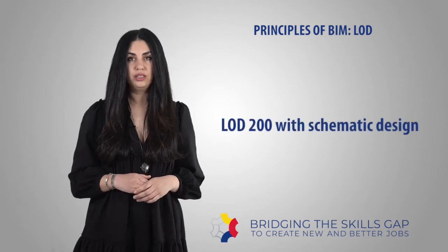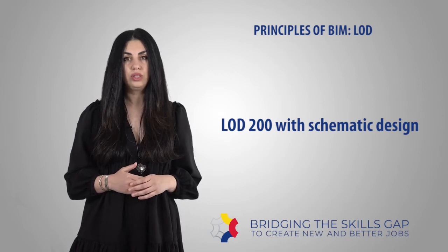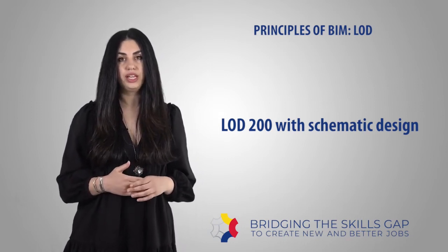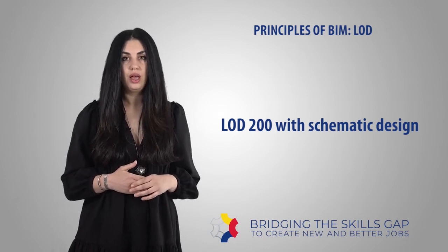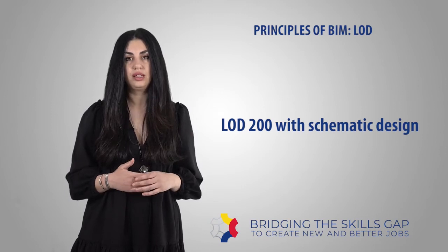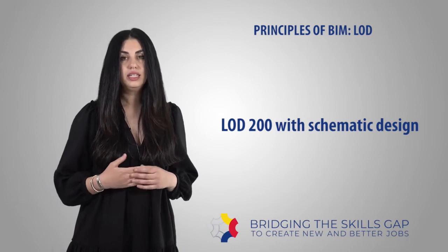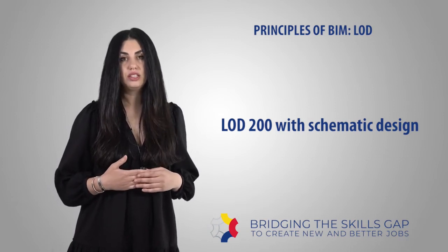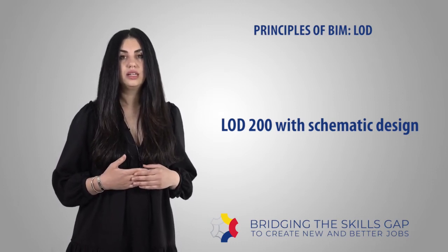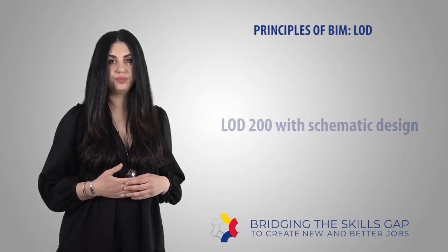LOD 200, schematic design, a general model where elements are modeled with approximate quantities: size, shape, location, and orientation. We can also attach non-geometric information to the model elements. With LOD 200, as you can see, this column starts to take the shape of a steel column. This level needs to represent approximate dimensions, shape, and location.